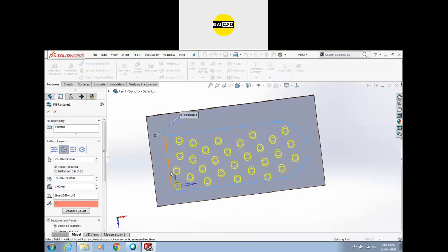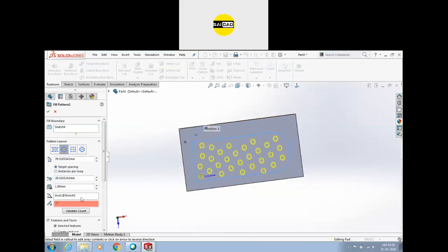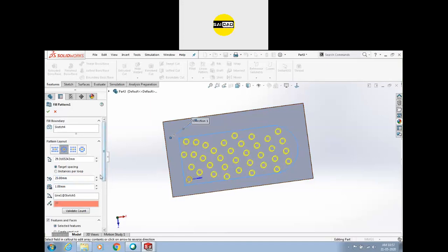You can see this is the center. This is the first one. This is the second, the third arc, the fourth arc. So there are the arcs like that option. Okay, you can specify the between angle. I want that angle to be 25. So you can see that.